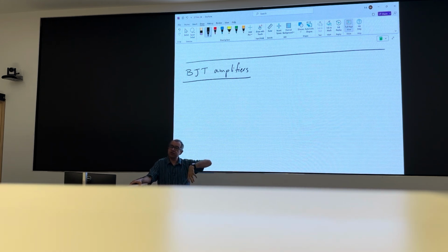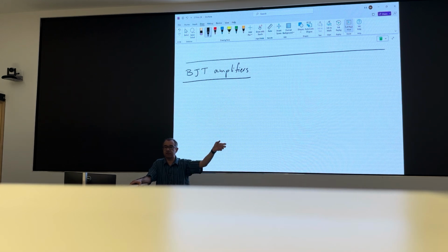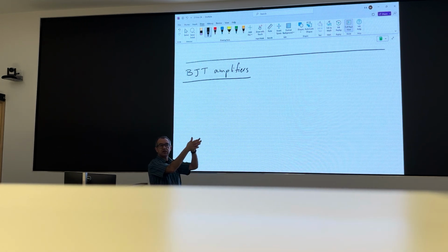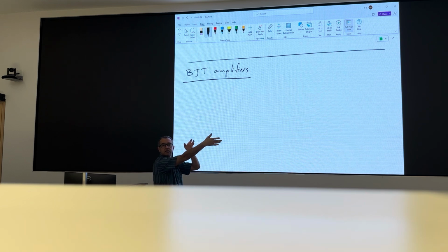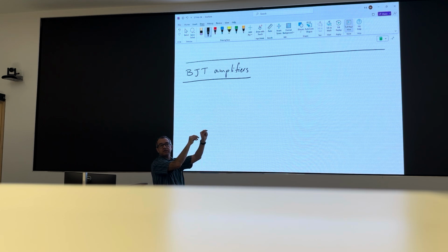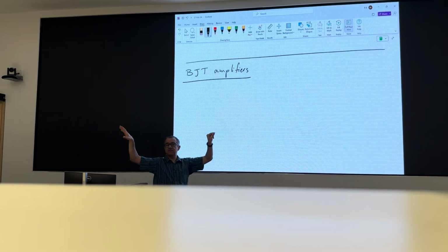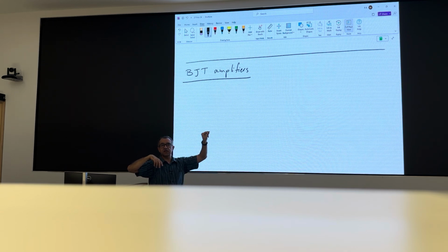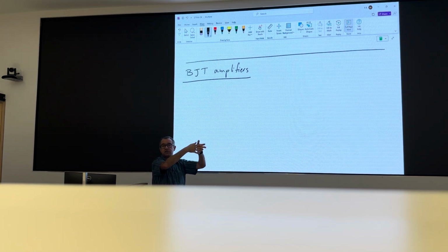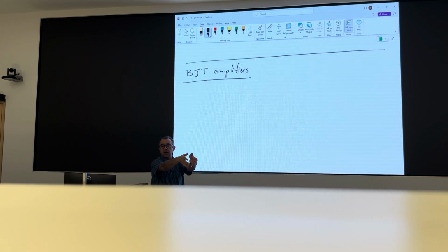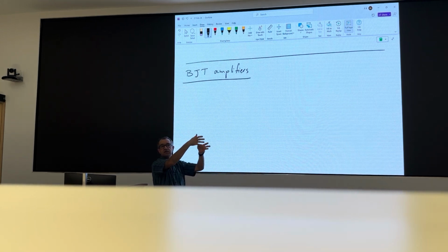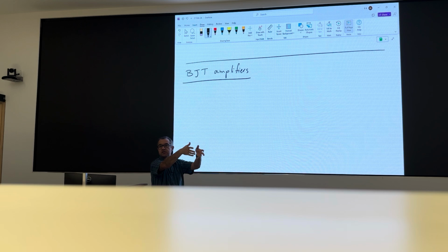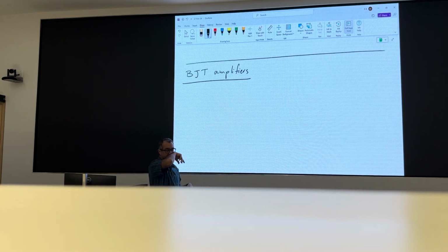At the input stage of any A to D, there is an amplifier. That amplifier isolates your A to D from whatever is happening behind it. It takes a sample of your input analog voltage and gives it to your A to D. Now you have time to do the analog to digital conversion. A D to A, digital to analog converter, has an amplifier at the output. Once you have these bits converted into voltages, you need that voltage to be used, so there is an amplifier right there.